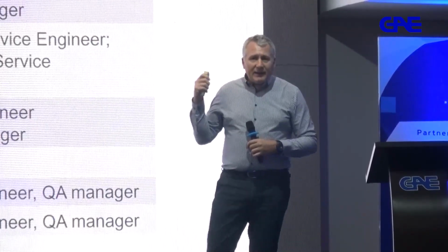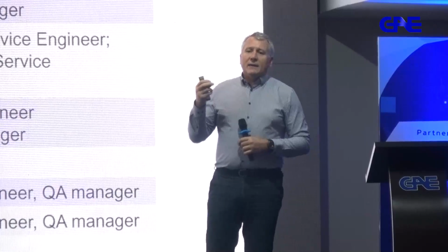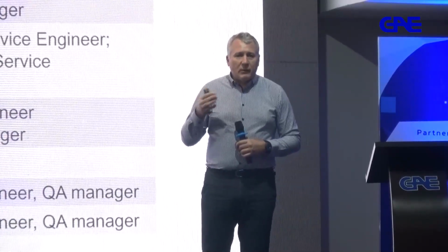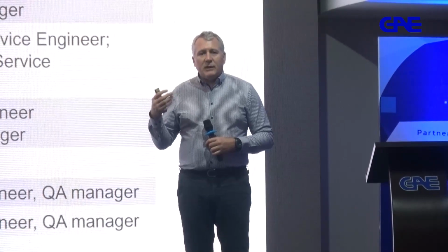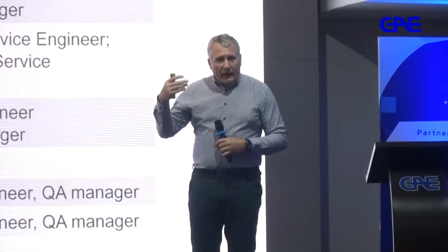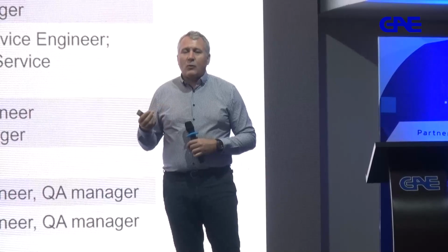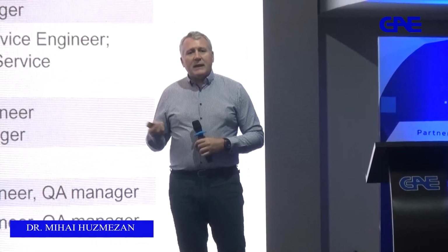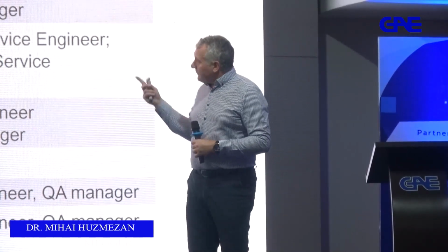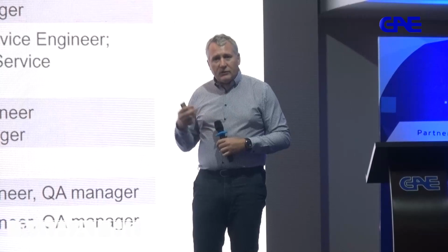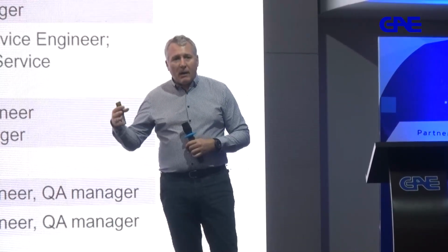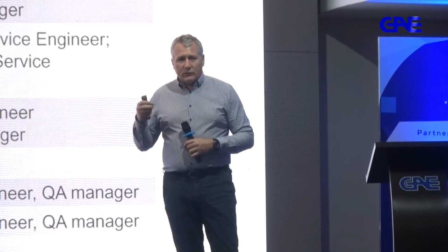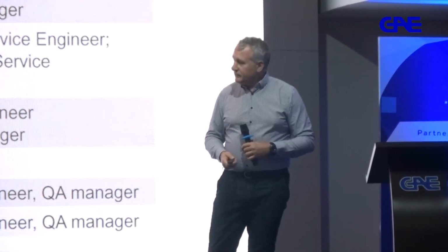And maybe here I can tell you a little story. Do you know that for partial discharge to be triggered, to have those electrons jumping, sometimes you need random cosmic waves, and of course waiting for that is not necessarily an option in production. So you basically can also trigger that by using X-rays. So our company will manufacture such kind of test chambers that are using the device I'm talking about here for acquiring PD information, are using other devices to actually power, and also the X-ray unit in order to trigger partial discharge.